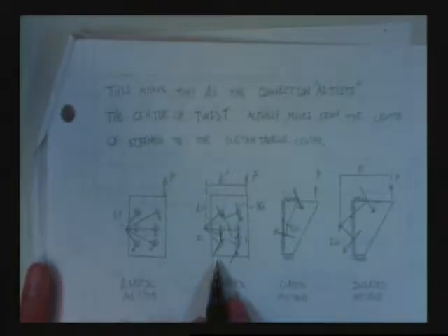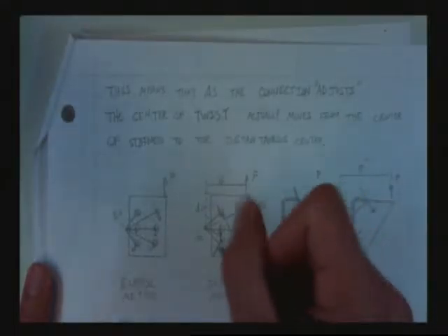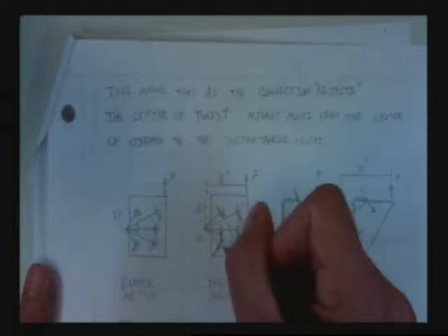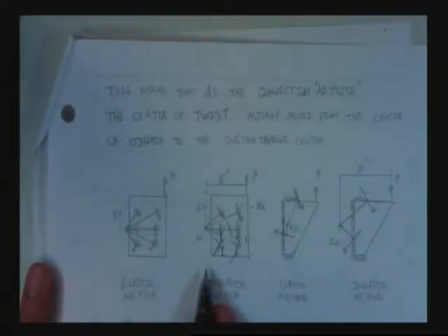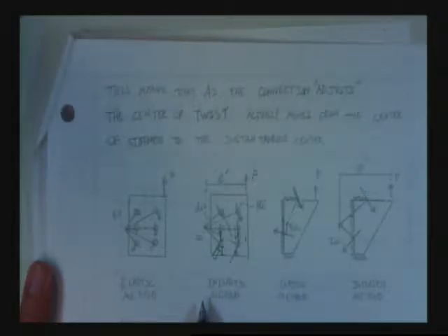Well, what's commonly used is the most conservative. So even though this is at this strange angle here, people will often use, if that is the lowest L sub C, that distance. Does that make sense? Because it's conservative. They don't want to have to think about, oh, it should be at an angle, and so it should be increased by 20%. They don't care. Pick a conservative one. It's another good reason to have a uniform bolt layout.